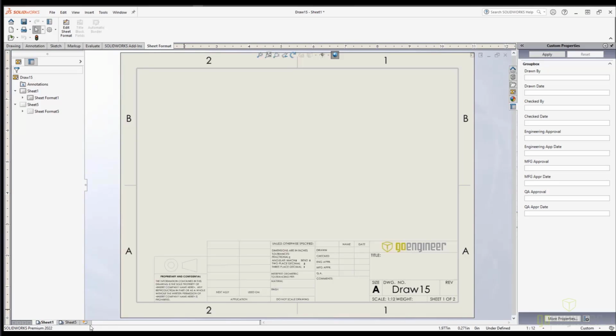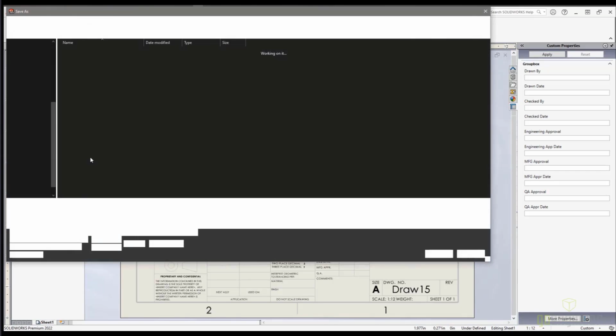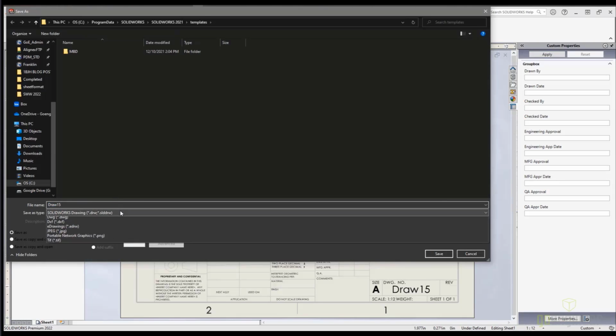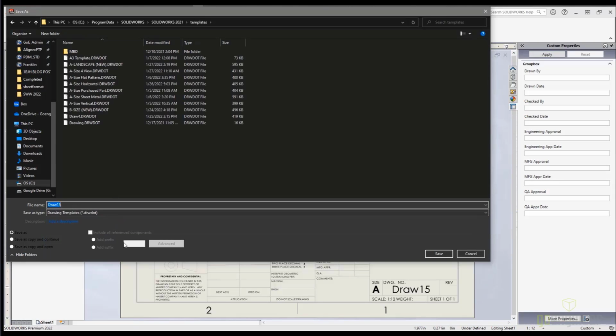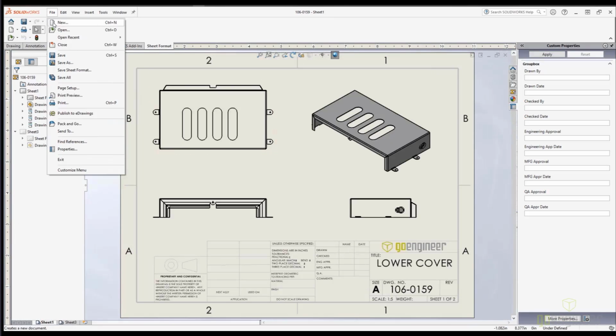Another thing you'll find. I'll go ahead and delete that. So what I was going to say earlier was if you want to save this so that it always adds that second sheet whenever you start a new drawing, you'll want to save over this drawing template file. So do File, Save As, and change the file type to drawing template, and then select your file to rename. So that will resave that document property and make sure you have that link to that.